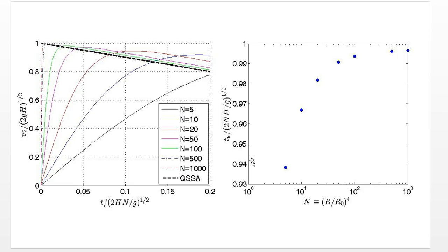And so the result is, as long as the hole or exit pipe size is relatively small compared to the size of the tank, the quasi-steady state approximation is extremely accurate for tank emptying problems. So as long as the hole is not as big as the entire tank, we can use the quasi-steady state approximation with good certainty and a high level of accuracy.